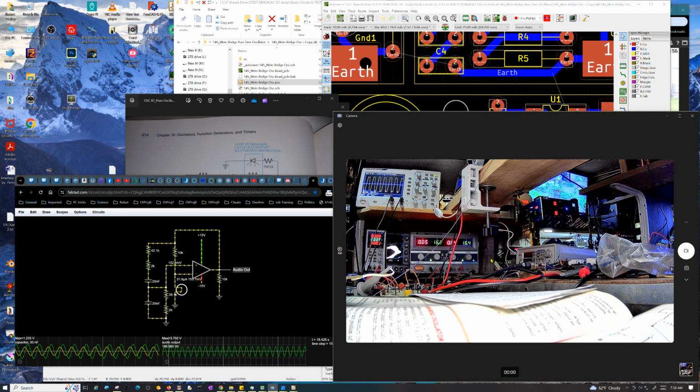This is at 91 kilohertz at this resistance setting, and we can go down as low as like 35 kilohertz with no resistor, in other words 0.2 ohms. But then we can go up to 203 kilohertz, and remember the slew rate tests I did on the 072, we're running into its slew rate limits, so it's forming a triangle wave now, of sorts, because it's still pegging it, saturating the op amp rail to rail, kind of.